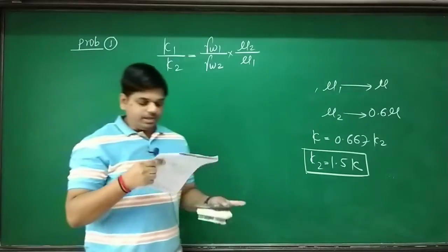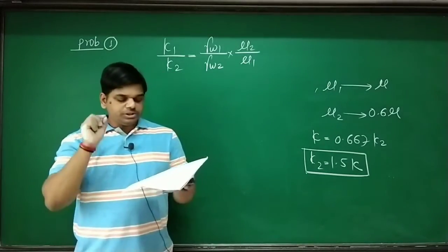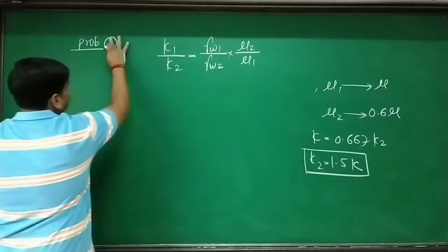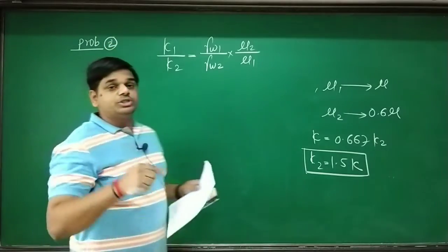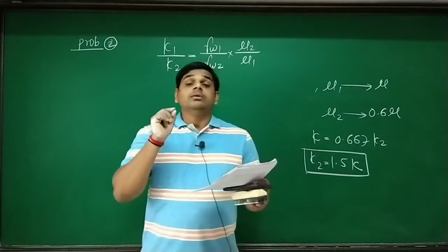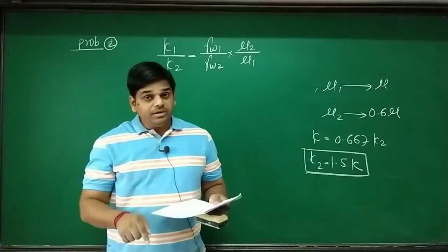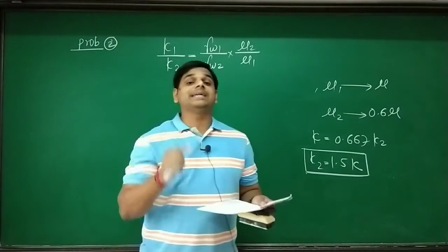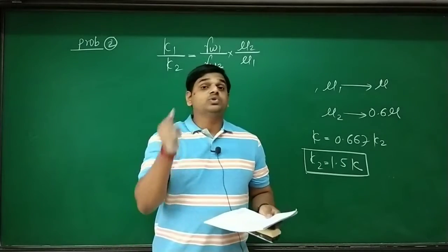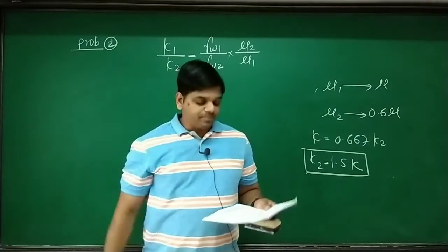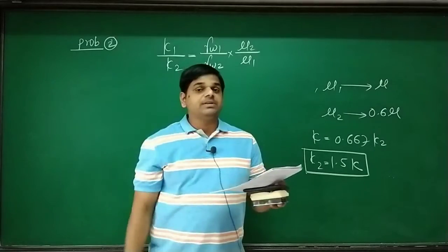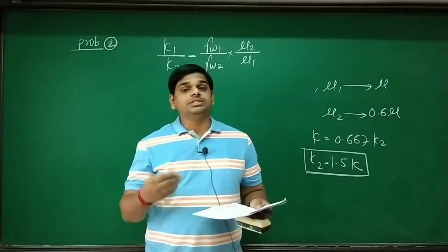Read the problem carefully. Due to change of temperature, in your problem number 2, unit weight and dynamic viscosity of percolating fluid reduces by 10% and 40% respectively. आता reduce to नहीं है, reduce by. Then calculate change in the permeability.